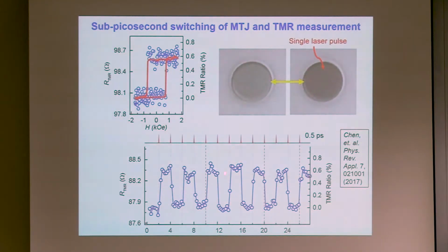You can see that the signal is very noisy. That's to blame on the low quality ITO we were using. The ITO gives you very bad contact and a lot of measurement noise. But nevertheless, another thing to compare is the magnetoresistance compared to the switching when you're sweeping a magnetic field.